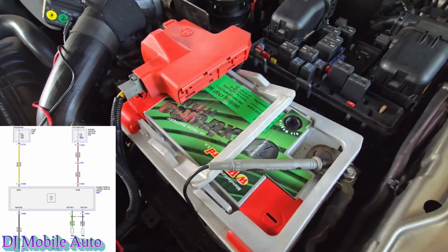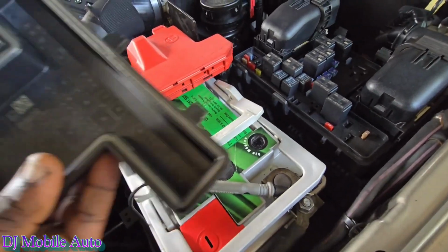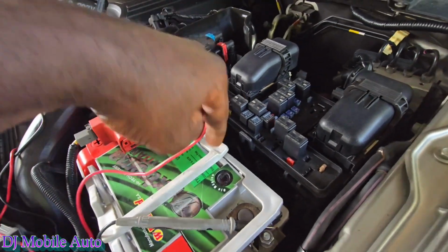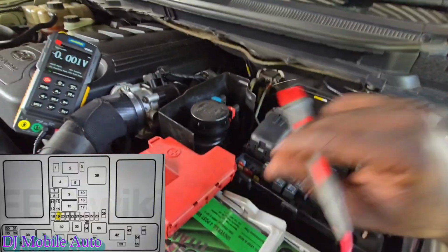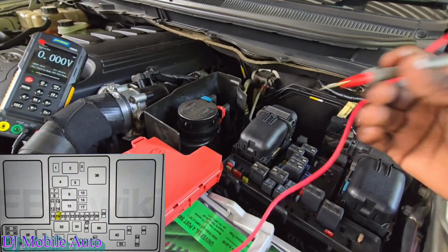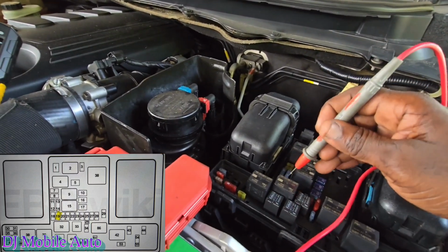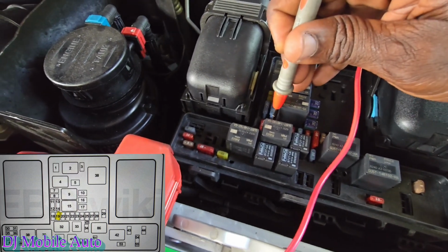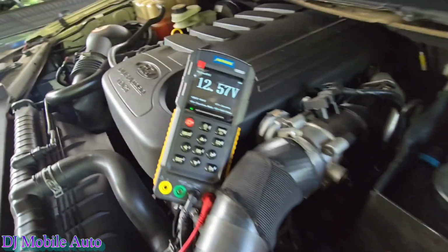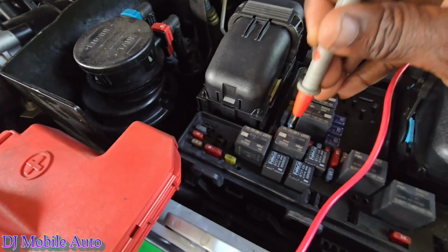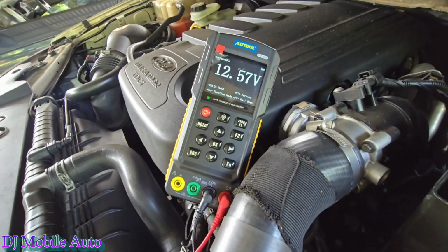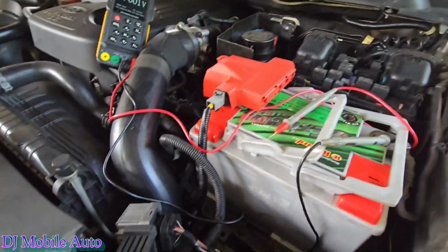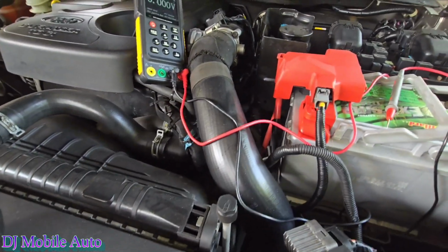So that's one. Next we gotta look for fuse 19, right? That's the fuse that's sending power to the module. From the scan tool, I'm seeing that the module is powering up, but we gotta check fuse 19, which is this one right here, and make sure it's a 10 amp. Make sure that it's getting 12 volts, which it is, on both sides. So I'm supposed to get 12 volts straight to that module underneath the vehicle, right?